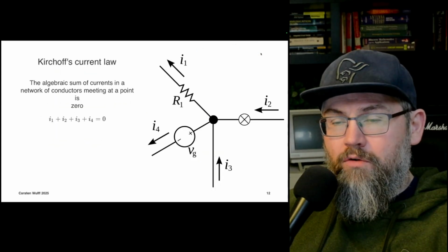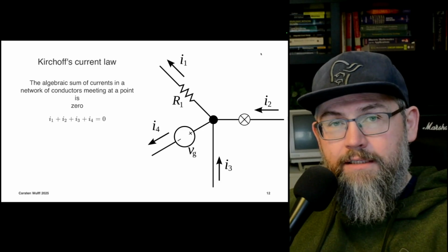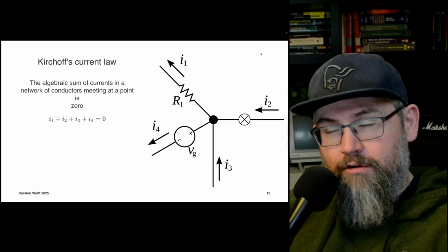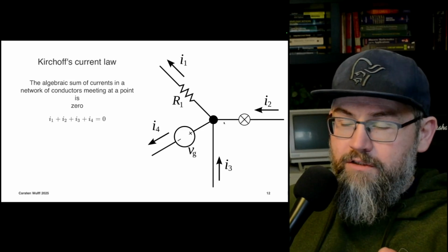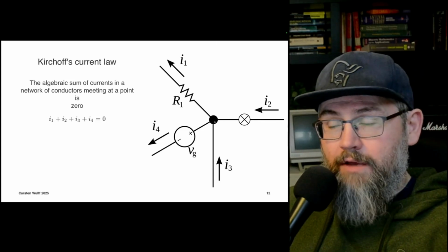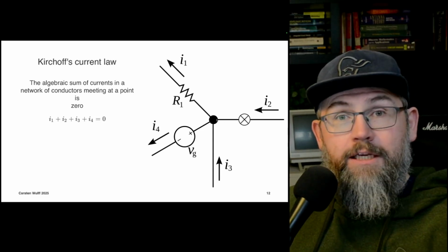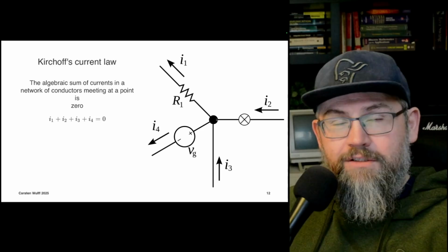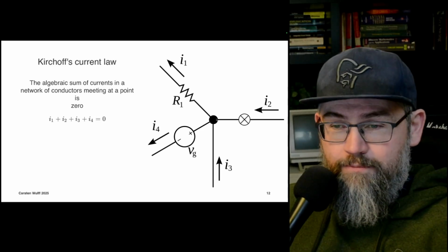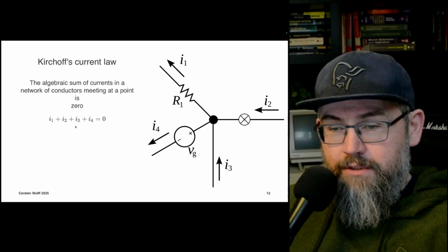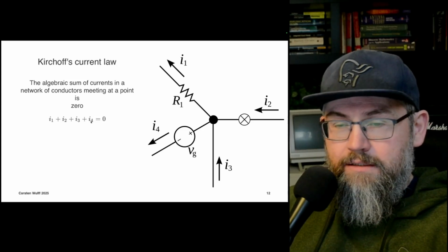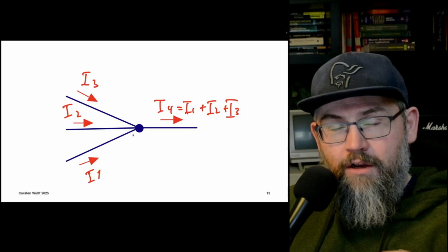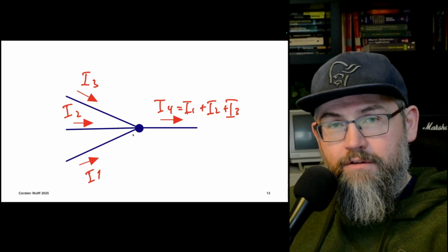Another way to add quantities is if you have the quantities as currents. Because Kirchhoff's current law tells us that if we sum all the currents in and out of a node, then it's going to equal 0. So any current entering the node must equal all the currents exiting the node. So that's what we say with this equation, which means that if we have a bunch of currents, we can just connect a wire together, and the wire will itself sum all the currents.